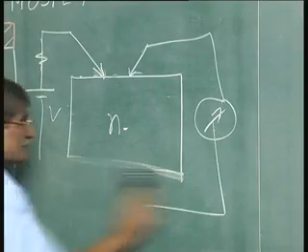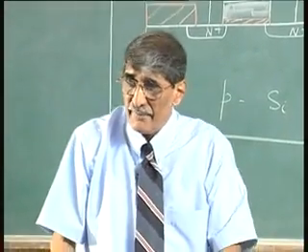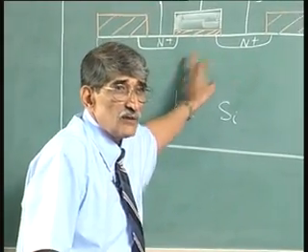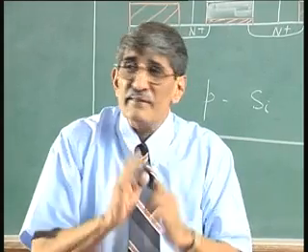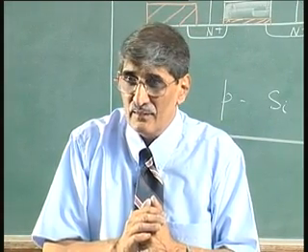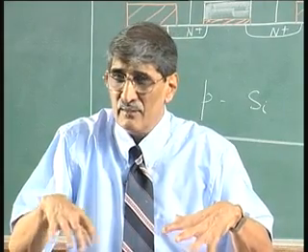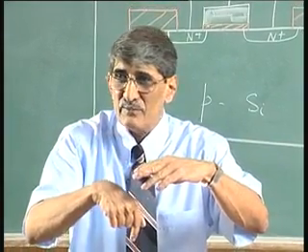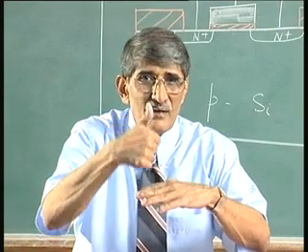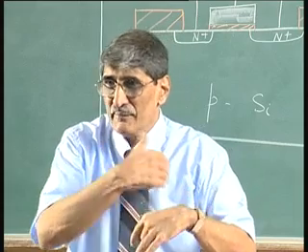Now, let us see. So, in a free surface, the problem is there. When you have deposited oxide, there will still be problems. If it is thermal oxide, the problem is not there, because those interface states, after all, what are those states, surface states due to? The atom within the bulk is surrounded by 4 neighbors. When it comes to the surface, on the top surface, it is 1, 2, 3 neighbors. Up there is no neighbor, so there is a dangling bond. The dangling bond is the one which gives rise to the levels.